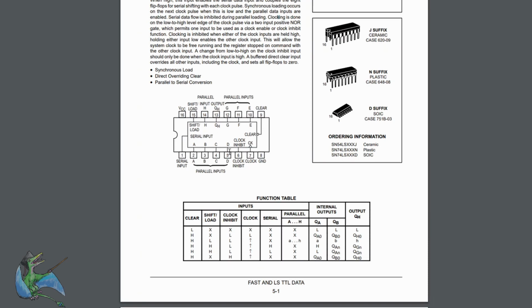So basically what this means is you only need to read memory once for every 8 pixels that goes up on the screen. And that's really important if you're talking about 1970s technology, because a 40-column screen requires a dot clock of around 8 megahertz. Memory from the 1970s could never run at 8 megahertz if you had to read it for every pixel you shoved out. So this allows you to do a 40-column screen with only 1 megahertz memory.